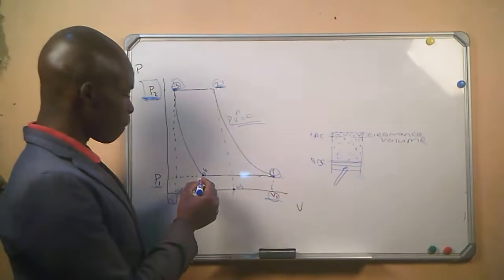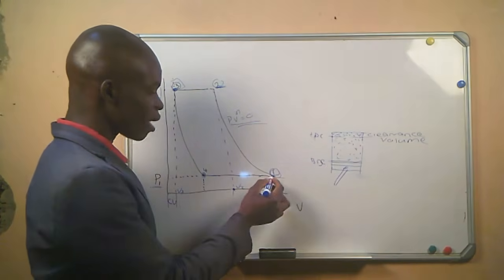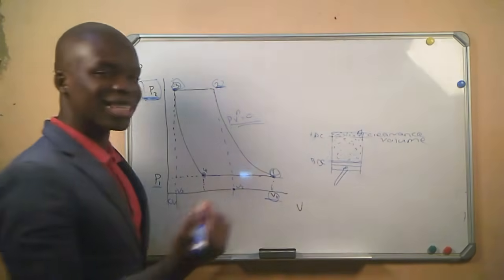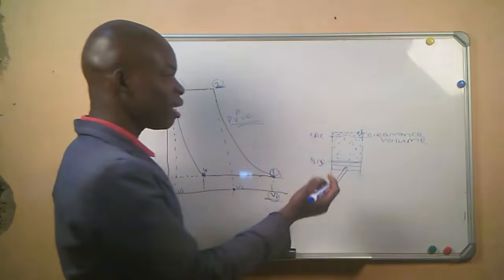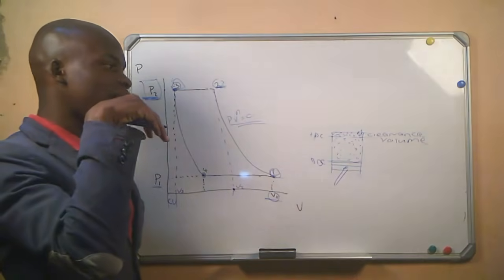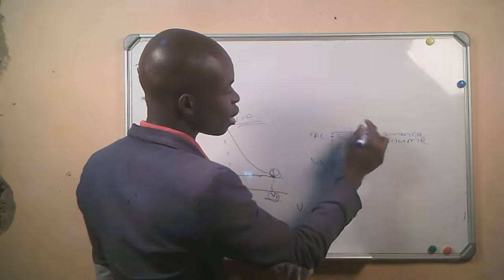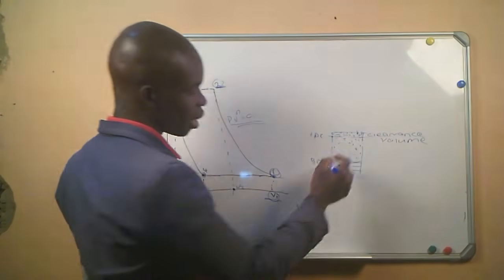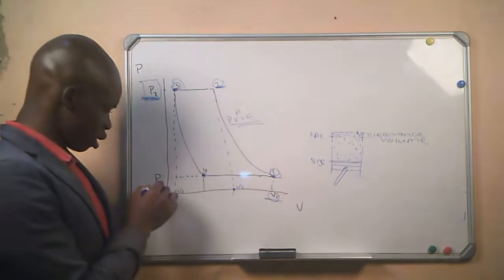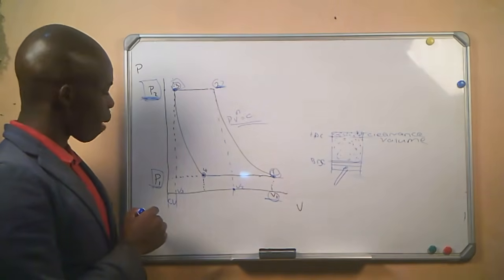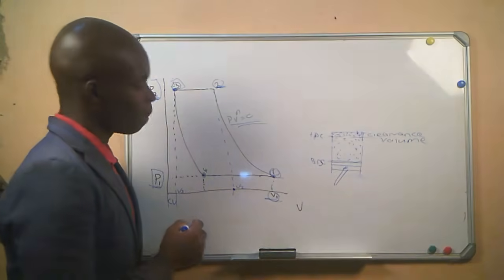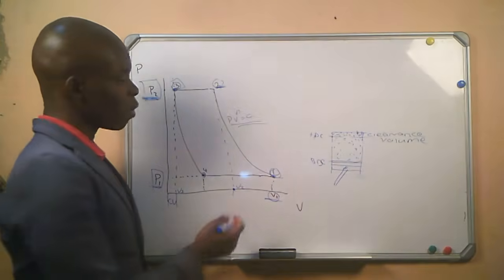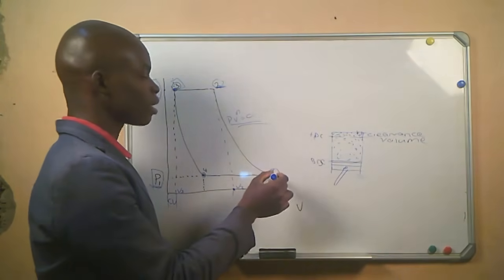And then from point number 4 to point number 1, one of the valves, which is the induction valve, will open, and then air will be let into the system from outside. This is going to be our pressure, which is pressure number 1, and then after it will close, now we have air in the system. We can begin our cycle again.